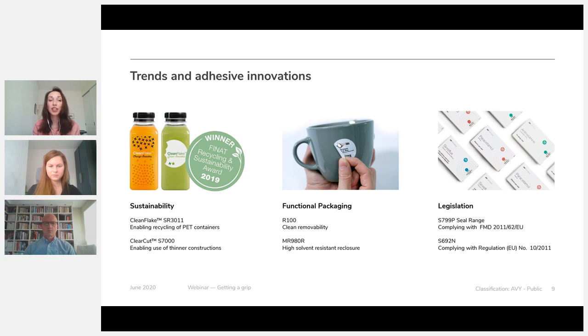This is an adhesive that we launched with thin materials, thin filmic materials. Think of polypropylene 50 micron face and PET 23 liner. This is the typical construction this adhesive is offered with, where we promise the convertibility, or the feeling that you get when running this material, on par with the thicker constructions that you are used to.